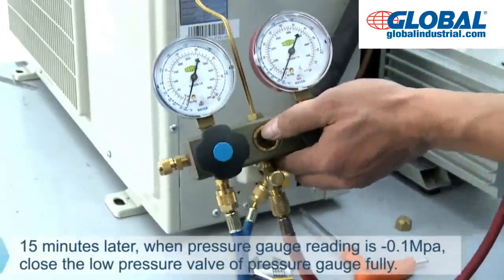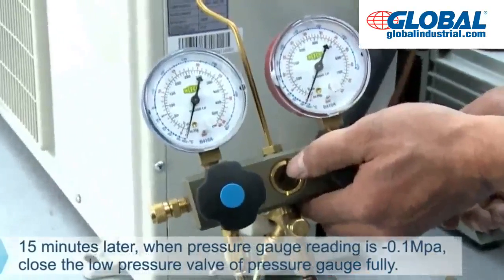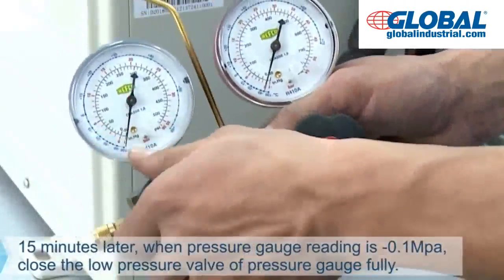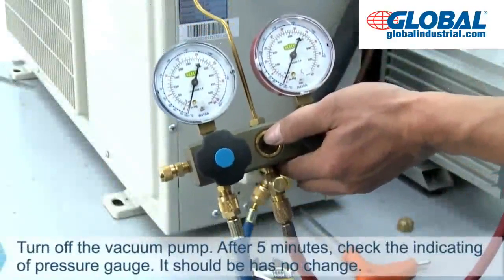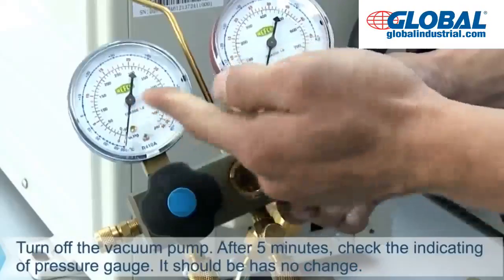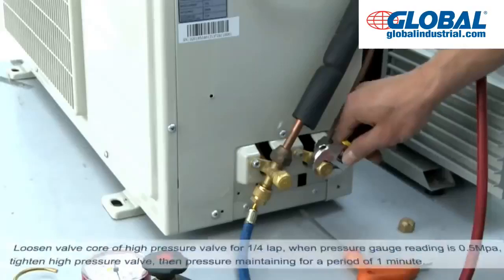15 minutes later, when pressure gauge reading is negative 0.1 MPa, close the low pressure valve of pressure gauge fully. Turn off the vacuum pump. After 5 minutes, check the indicating of pressure gauge. It should have no change.